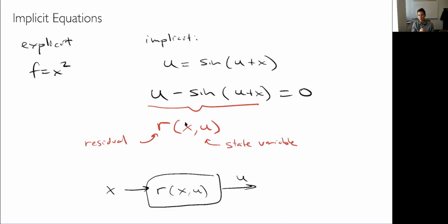In finite element software, it's the same thing. You can't actually compute the stress directly. We have to solve a system of equations to figure out what the deflections are. Those would be the states. We're trying to figure out what deflections satisfy my boundary conditions for all the forces and boundary conditions like clamped ends. I put those boundary conditions in and solve this residual equation to figure out what the deflections are. Once I have the deflections, that's my state, and I can compute stresses. So there's a solver that occurs there. If you've looked at some bigger problems with finite element software, you may see that it's actually doing some iterations. This often happens in analysis: there are things we can't compute directly, so we have to iterate.